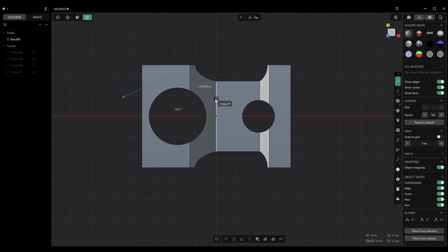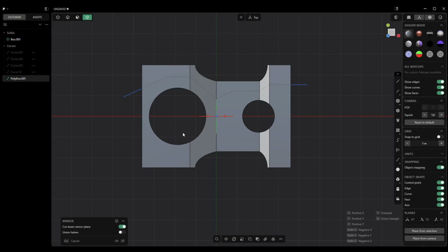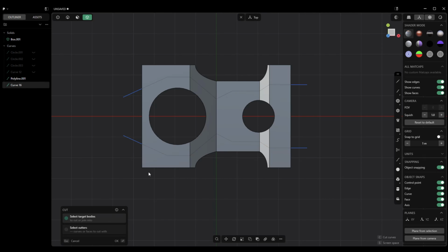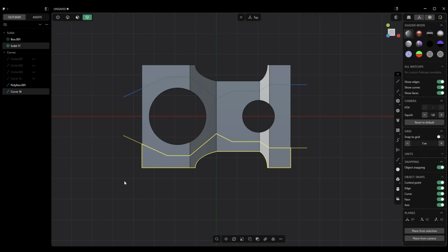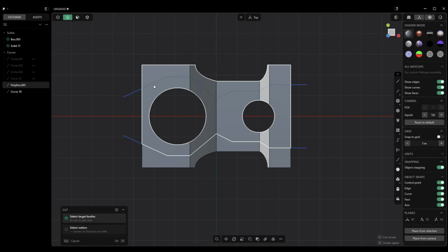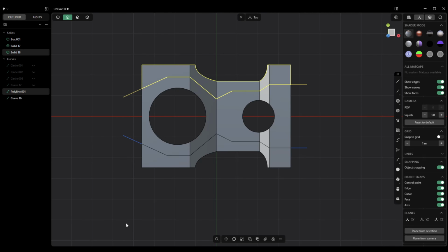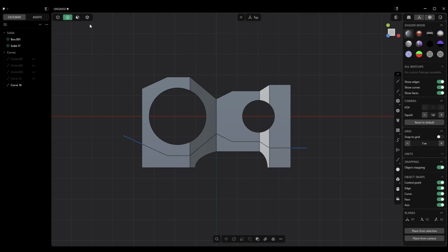And I already cut that section out, I'm aware of that, but for demonstration purposes, I'm going to do something like that, right? And same process, Alt-X, move that down, click on OK, hit C on the keyboard to grab this guy, click on OK, then go and grab this guy, hit C on the keyboard, click on this guy, and OK. And then we can delete the top, we can go in object mode, delete the bottom, and we can go and hide that curve. All right.